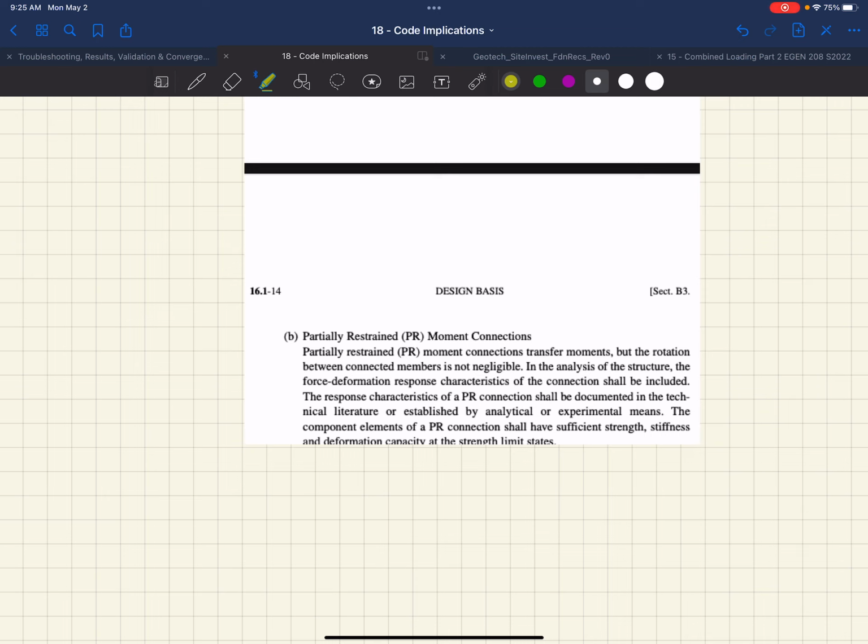All of those pre-configured connections have had that kind of analysis that you're talking about already done to them. So researchers have already figured this out for us and come up with different configurations. We trust that. They tell you, AISC tells you that if all of a sudden you've got another row of bolts, now you need to consider the moment on the bolt group. Whereas if you have a single row of bolts, you don't have to do that.